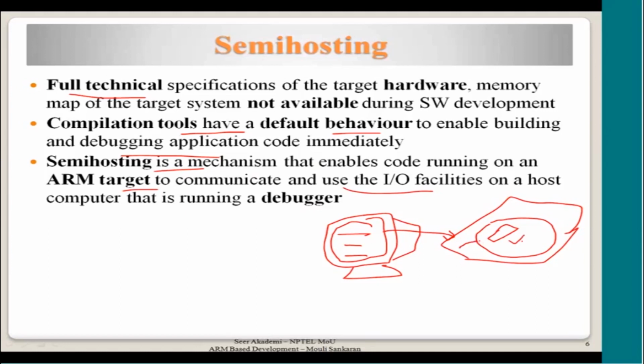But there is some piece of software here also, which is specific to the debugger, so that it can communicate back to the debugger running on the PC with some information. So this is not exactly a target hardware. It is not a standalone hardware because it is connected to a development platform, a PC, and a debugger is there, and as a user, we are interacting with the hardware and getting the responses from there. So it communicates using the I/O facility of the debugger.